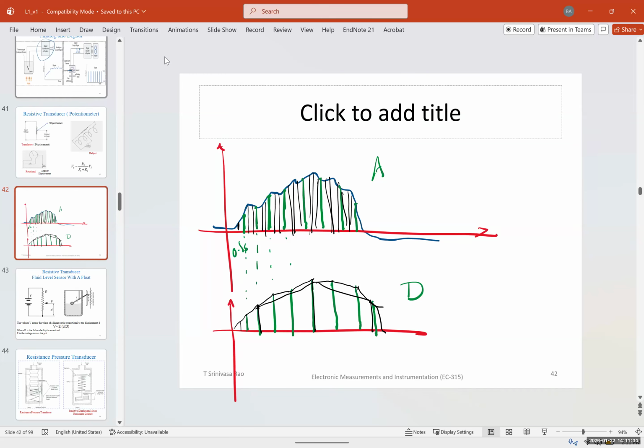Like in the previous example, if you want to take temperature, and the temperature goes a little bit down in 0.1 second, it's not going to make a difference in our thermostat. So we want to put the sampling further apart, because if we do that, we spend less energy on the analog to digital converter, and it's less data to transmit.